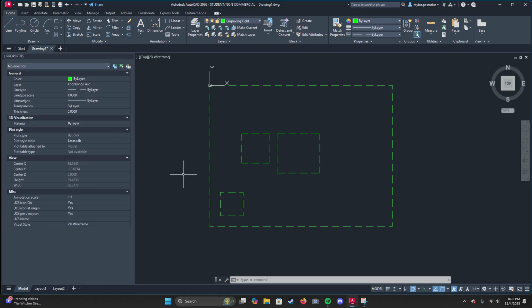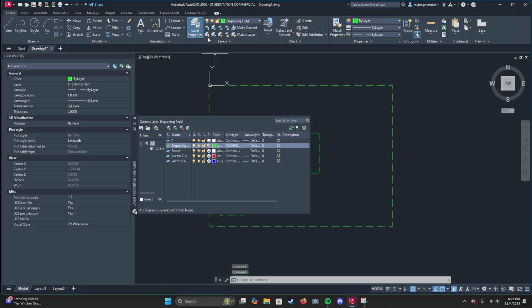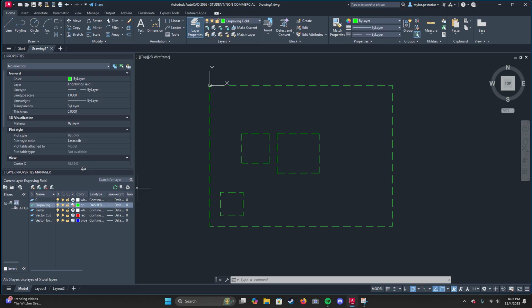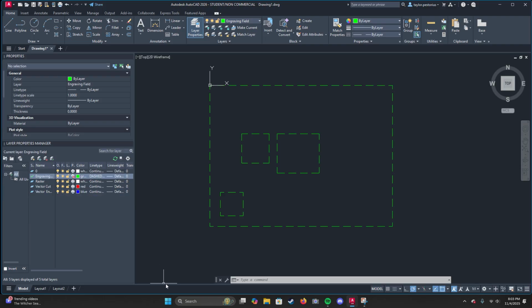And I'm going to make this come out. Perfect. Then I can do the exact same thing if I go down to my layers. Layer properties, rather. Thank you. And I take this and I bring it over here. And I like having those. Now, why is that? I'll tell you why. It's because when you are doing anything on this laser cutting template, you have 5 different layers.